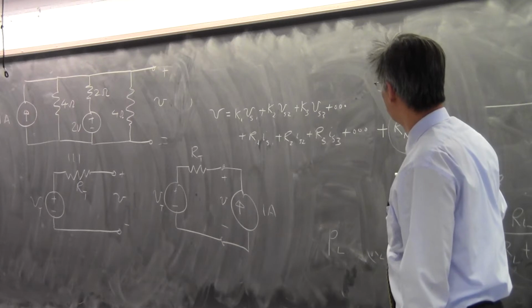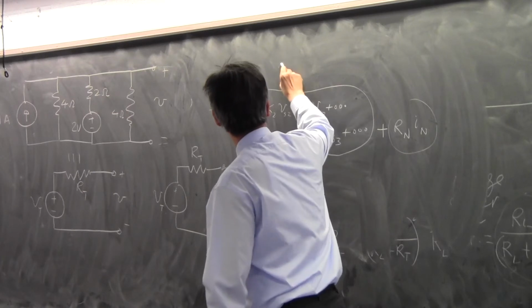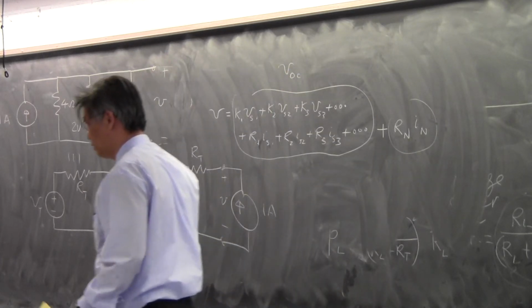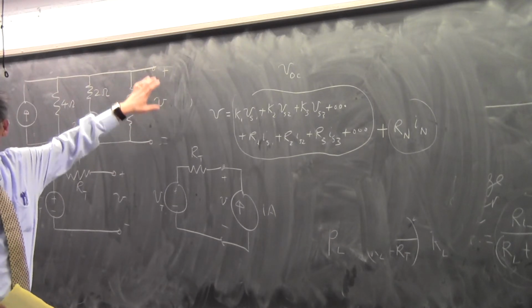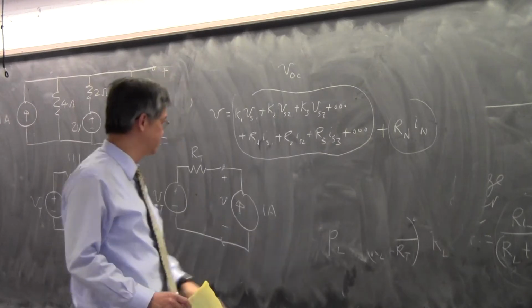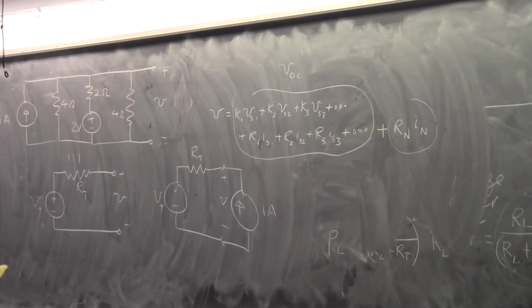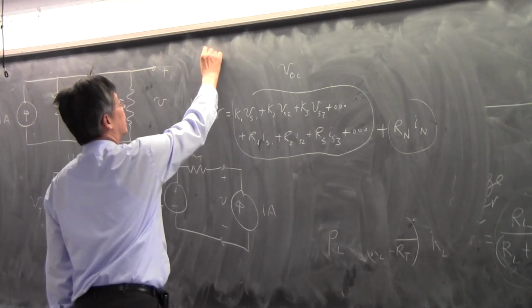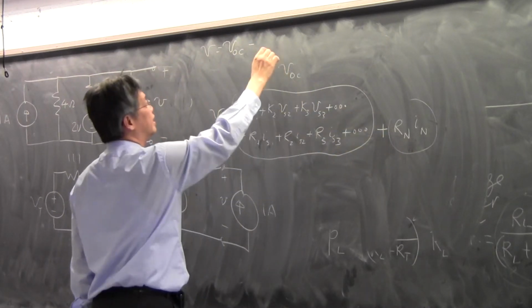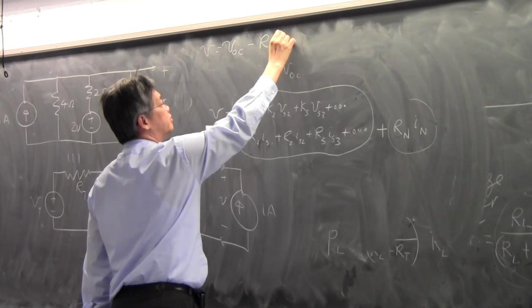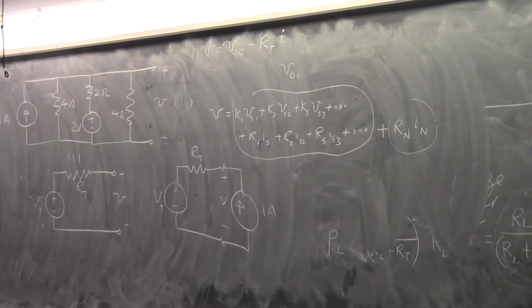So that means that this big piece here is just the voltage of the system when you have open circuit. That is, if you do not allow any current to go through this line over here, then this last term must be 0. And this must be the open circuit voltage. And hence, any voltage that I have can always be written in terms of open circuit voltage plus a linear term in I. And the linear term you can later prove to be the R Thevenin times I.